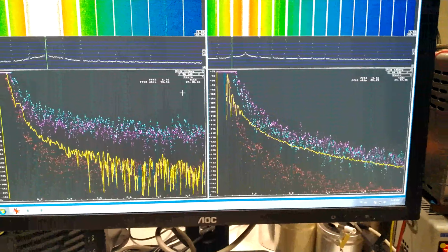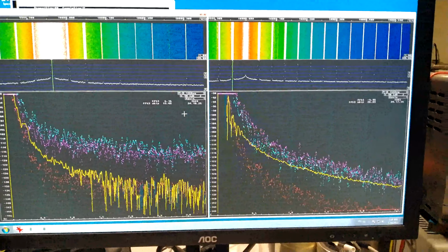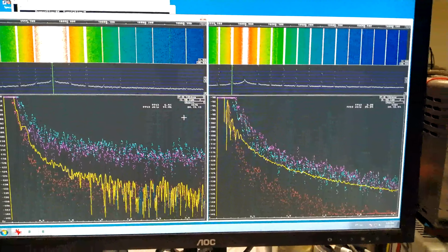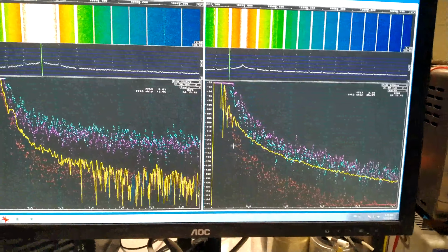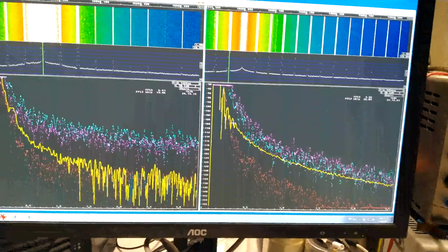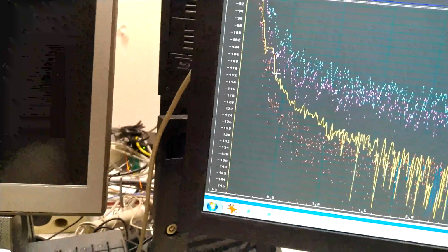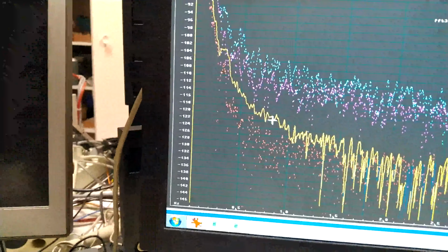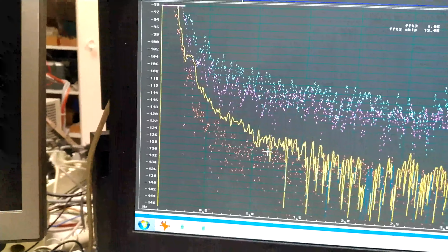I have set a very narrow bandwidth for the filter from which I extract the carrier for the quadrature detection I am using to get phase modulation and AM modulation. It is obvious that the data I get is not okay below about 0.3 Hertz. That's here with the sound card. And with the SDR IP pair, it's about the same, maybe 0.4 Hertz. Now, the signal is not far above the imaginary part, which represents the noise level.